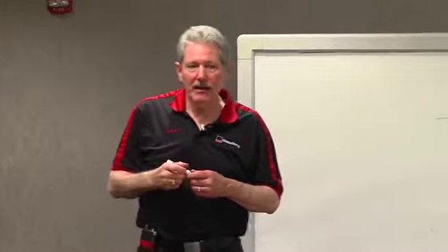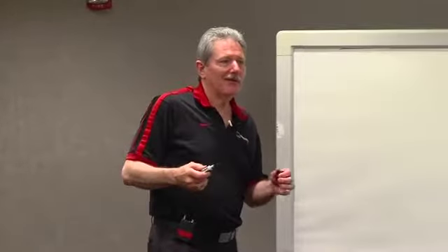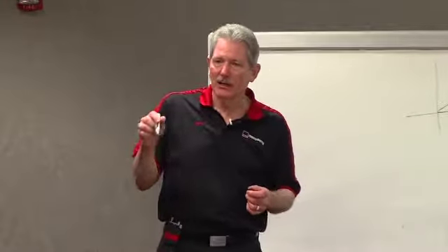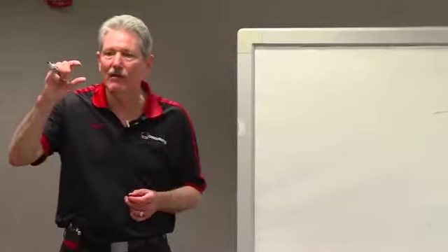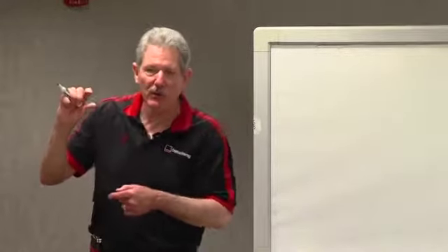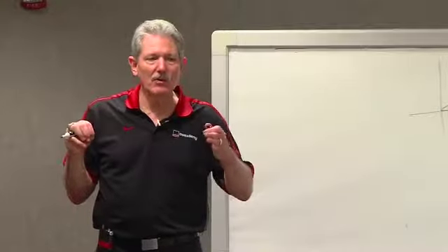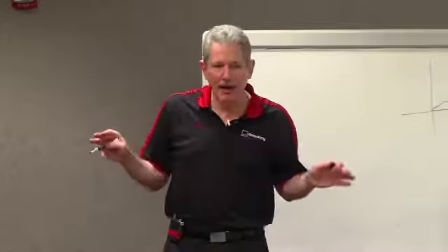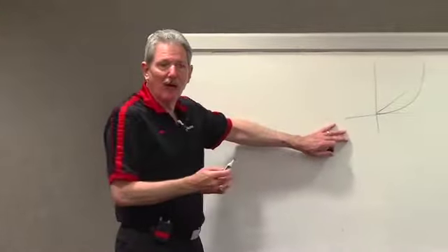The good thing about it is you can get MOSFETs that go down to 5 milliohm. They have MOSFETs today that are less than 1 milliohm. So for every 1,000 amps of current that goes through it, you only get 1 volt drop. Today, with 35 amps, we've got 1 volt drop. So a MOSFET, that's the reason why we're changing our diodes with the MOSFET rectifier bridge. Today, nobody uses transistors because of the problem that I told you, power.